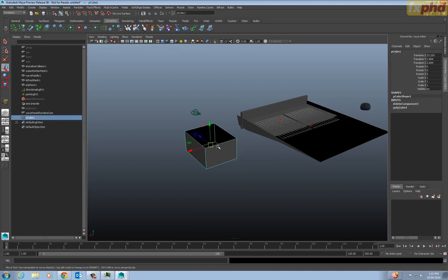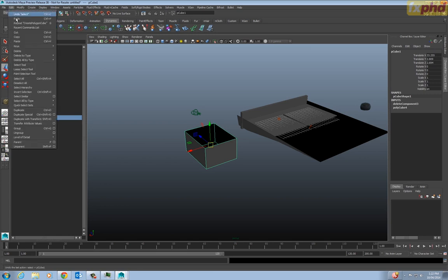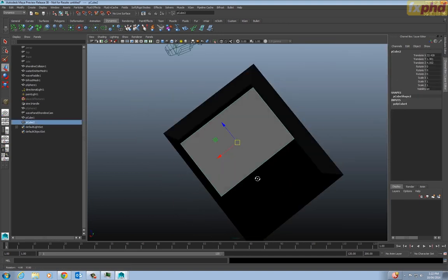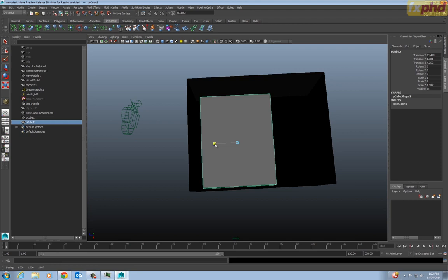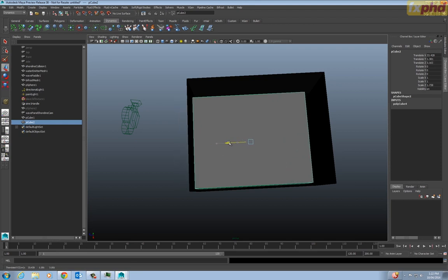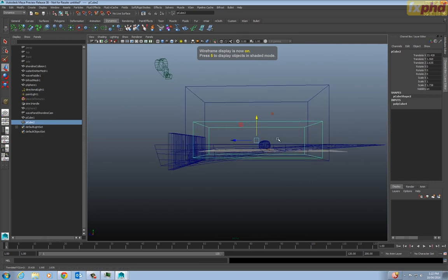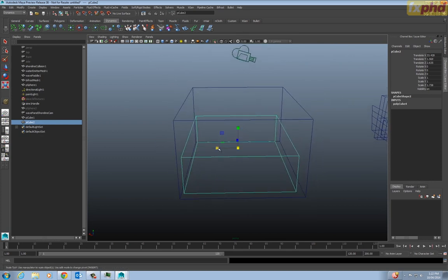So the reason why we imported that wave paddle scene was this cube that's on the left is totally new Bifrost colliding objects, but if we'd set the scale of this 1,000 times bigger, the simulation might actually not run correctly because the scale is too big in terms of size. Or if I'd set this box to be 100 times smaller, the scale of the water simulation would be too small. So you can always adjust this in the settings, but it's best to be careful with the